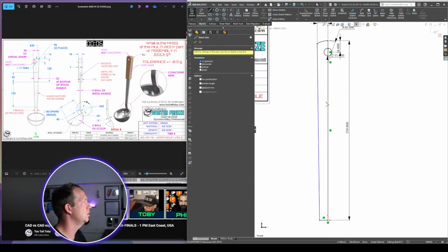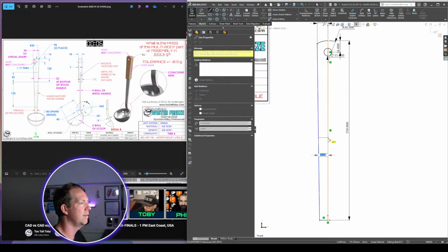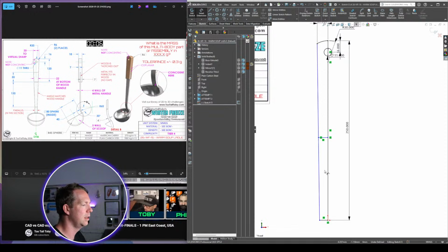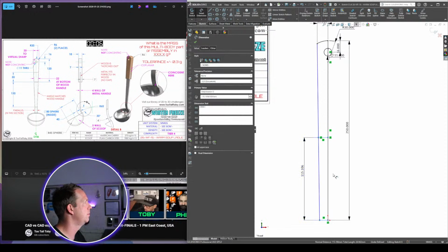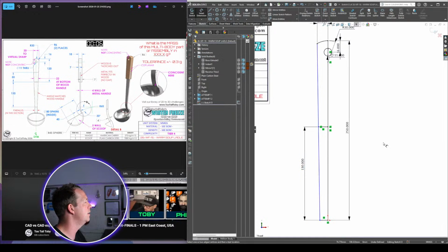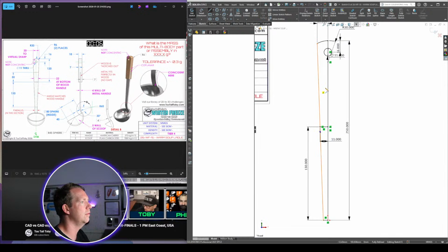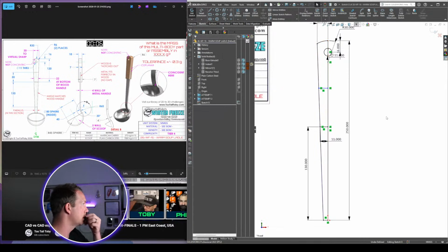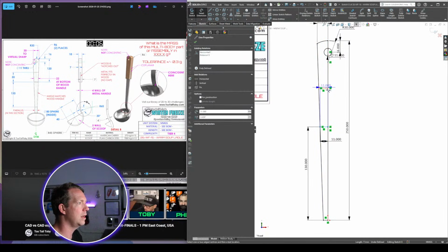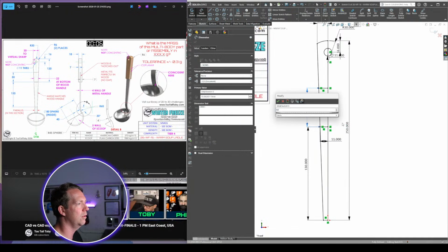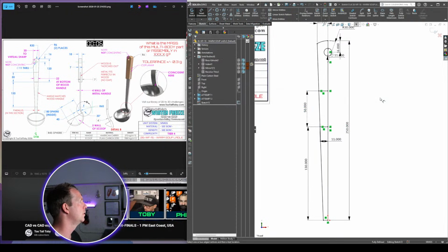And then I'm going to draw in 2 lines here. I'm going to have a solid line here. This one is at 130 from the bottom. And the 131, bottom of the wood, that's the wooden handle. That's going to be the 11 dimension, and that sets my angle. And then if I want to, I can draw the second line in, dimension that as well, and just keep that there. That's for how high the metal comes up. So I think that's everything in my sketch.